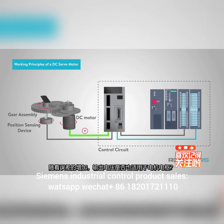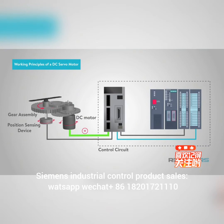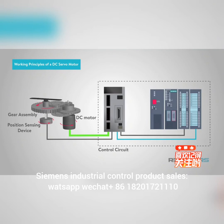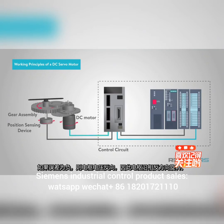As the error increases, so does the output voltage applied to the motor armature. As long as error exists, the comparator amplifier amplifies the error voltage and correspondingly powers the armature. The motor rotates until the error becomes zero. If the error is negative, the armature voltage reverses, and hence the armature rotates in the opposite direction.